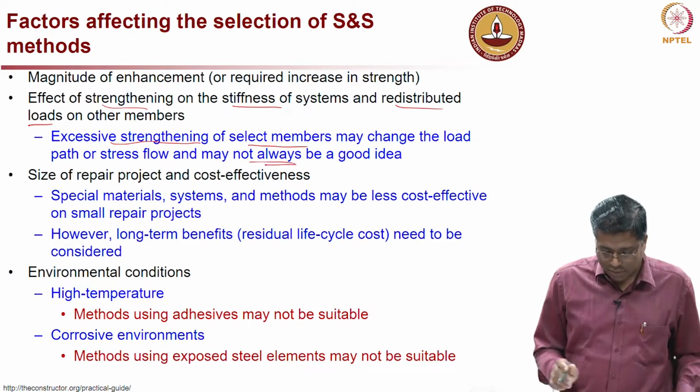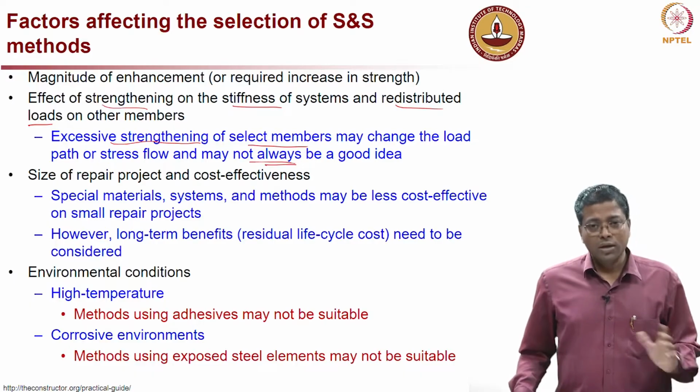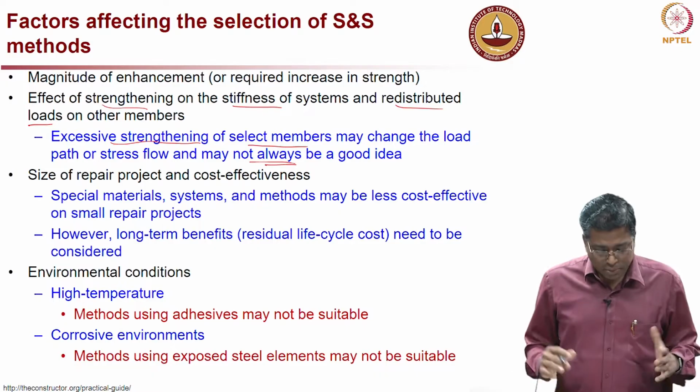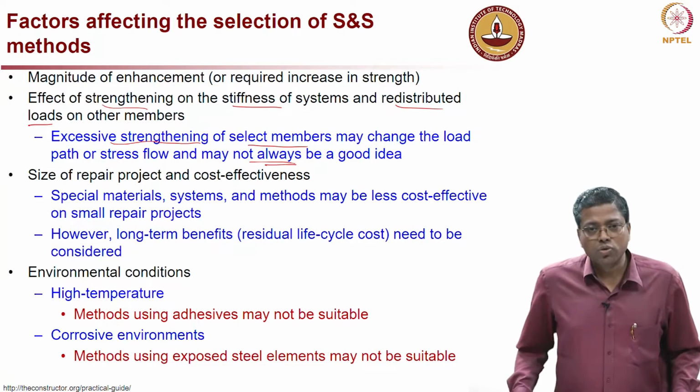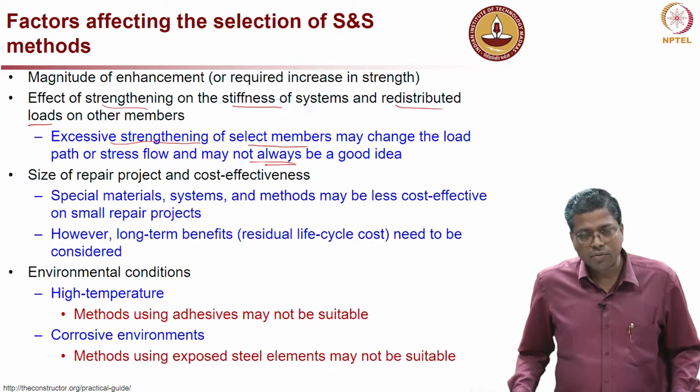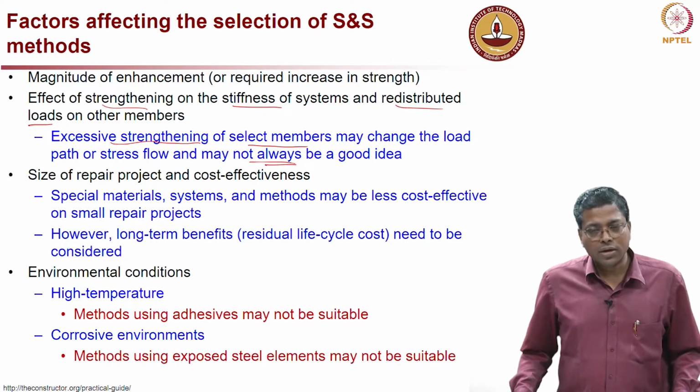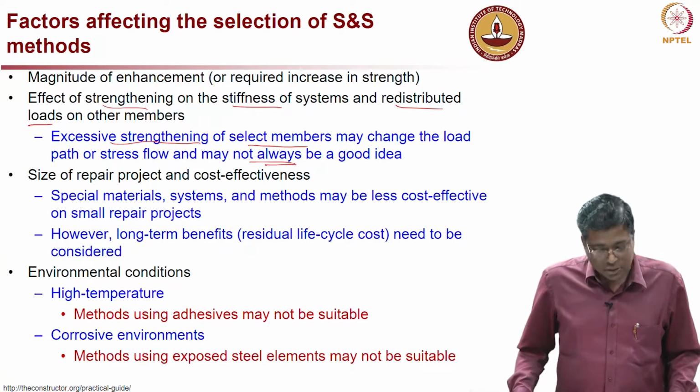In general, you might feel that it is good, but not necessarily always. For example, if you are putting too much steel reinforcement than what is required, then you might convert an under reinforced structural system to an over reinforced structural system, which is not a good idea.